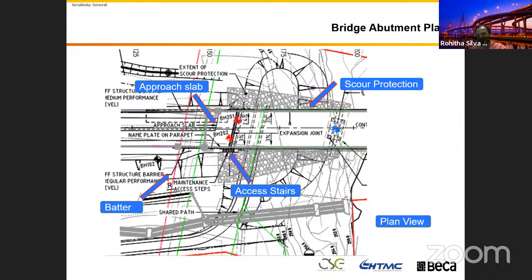They allow the bridge to settle gradually, or else they build the bearing units and let that one settle, then the soil settles, but gradually. When you are designing a bridge, that settlement interfacing you have to do all depends on the ground conditions.